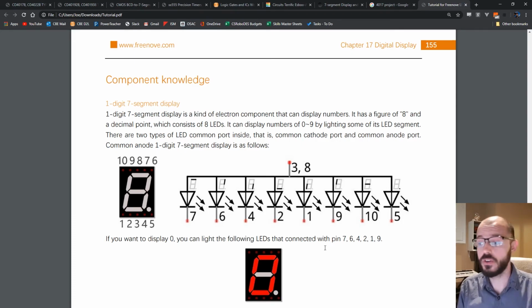So you can figure out a way to invert that signal and make the lows highs and the highs lows. You can use the NAND gate to do that. You would need a separate NAND gate for each of these, and you only have 4, so good luck.